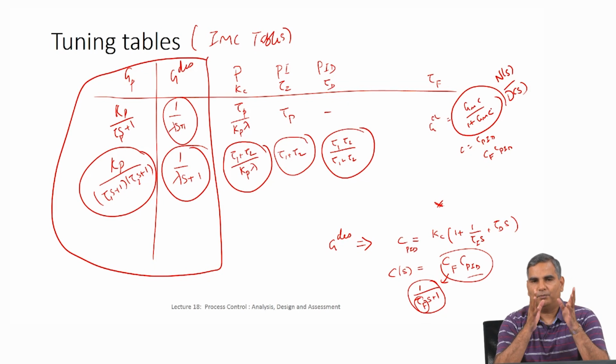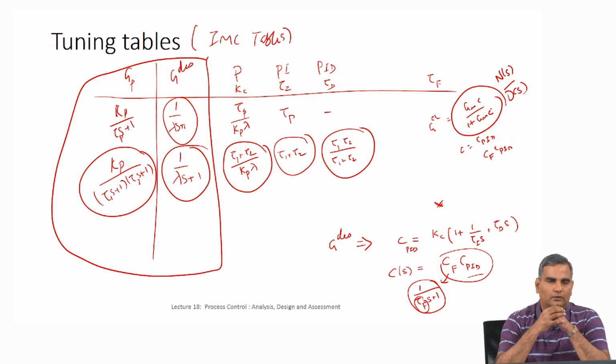So the inputs in the open loop, which are U(s) and D(s), now get transformed into Y set point(s) and D(s). Okay. And then in the open loop we have a transfer function between Y(s) and U(s), Y(s) and D(s), and then you can add them to get the overall effect on Y because of the linearity property. The same thing translates to closed loop.